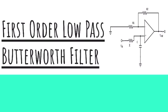Coming next we have the first order low pass Butterworth filter. The circuit shown here is the first order low pass Butterworth filter. The required passband gain of the Butterworth filter will mainly depend on the resistor values R1 and RF, where RF is nothing but the R2 here, and the cutoff frequency of the filter will depend on the R and C elements in this circuit.